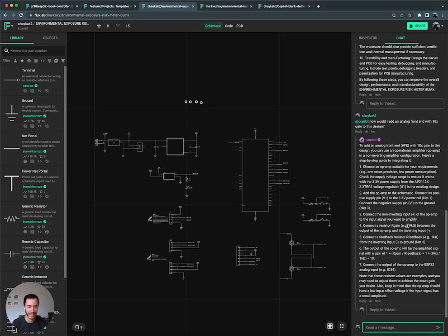Damn, that's pretty nice. No offense to junior engineers that I've worked with, but often I have found that we have that problem where we choose a part that doesn't work with the current voltage requirements of the system. And you're not going to add an entire other voltage regulator just to run one subsystem. It's much more efficient, well, you could if it's really important, but it's much more efficient to just sneak another part in here. We want to use the voltage systems that we already have in place, the voltage rails.